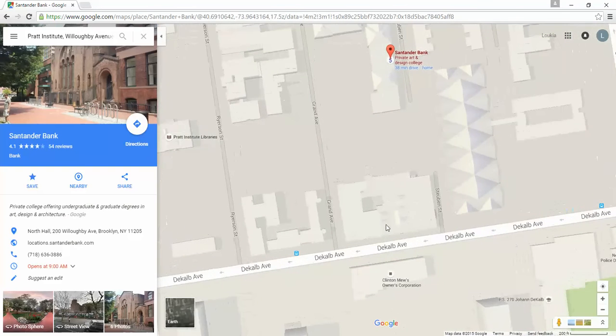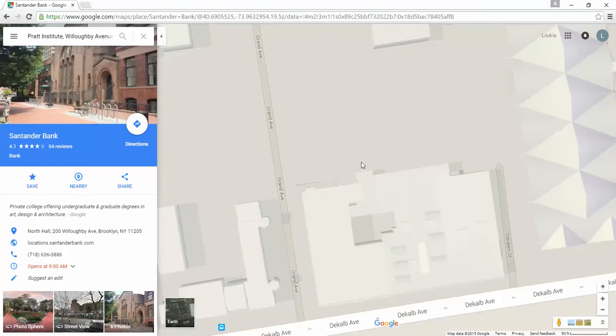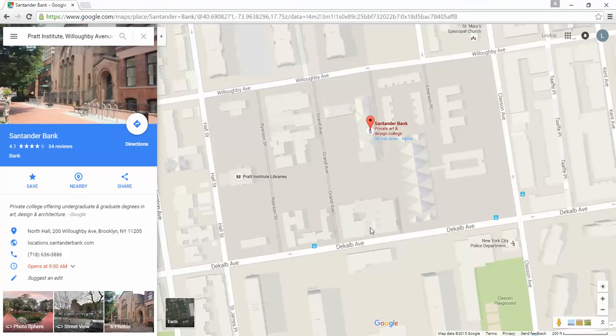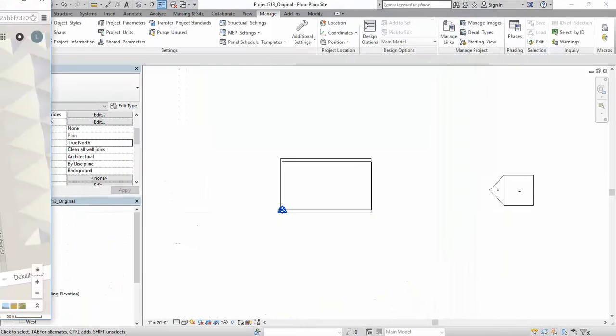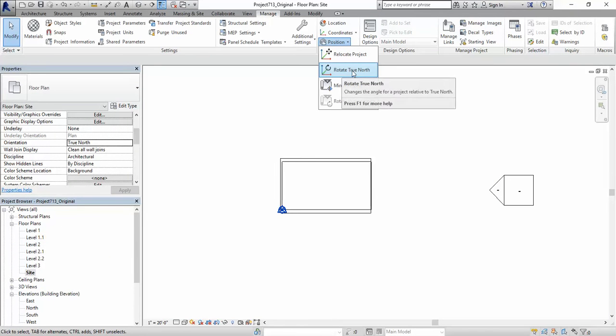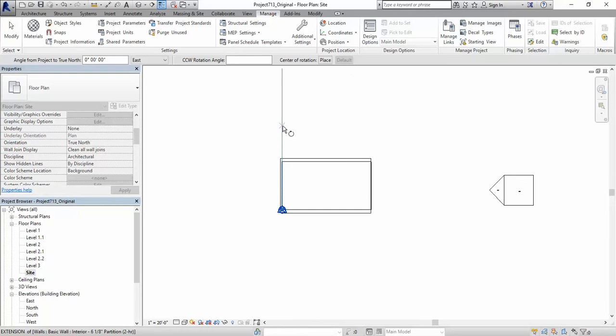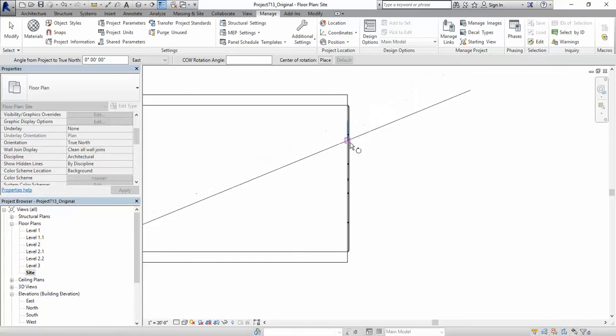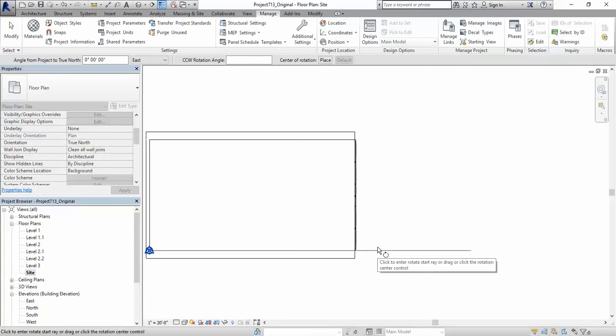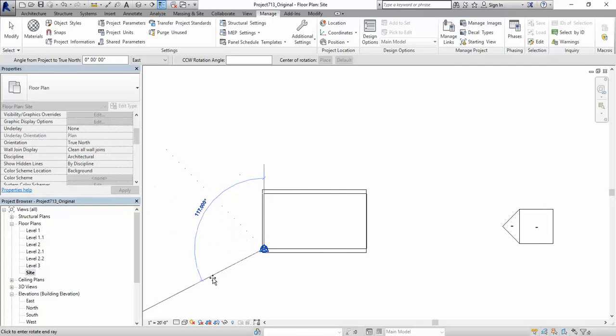If you guys zoom in quite a bit, this is the building we're working with, and I think that this is the gallery space itself. So if north is oriented all the way up perpendicularly, then we are, let's say, a little bit offset of the north, counterclockwise. So keeping that in mind, I will go ahead and rotate my building in such a way that the storefront, which is basically this facade, I can already see here my curtain wall, should be oriented approximately to the north itself. So I will go ahead and rotate, let's say 110 or something like that degrees.